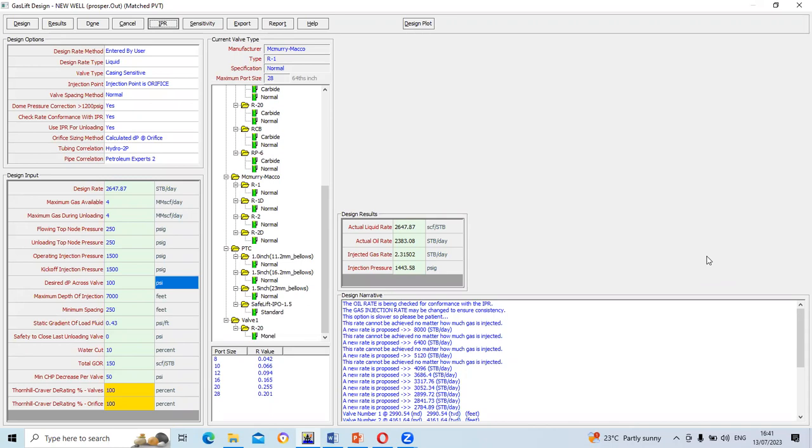Maybe we have done analysis for what we did the other day and what we have done today for dual porosity and for a deviated well and all of that. And then you want to carry out gas lifting. Now what you have to do is start a new project. Don't go and work on what you have already worked on before, because there are some things that along the line will not match, and once they don't match, it becomes a problem.